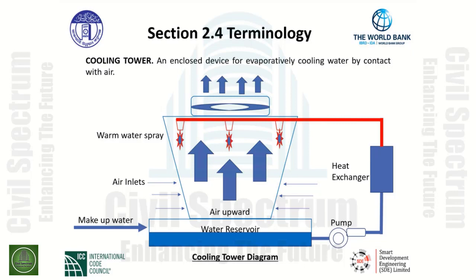The water reservoir must be at a certain level, not to be below the pump level. Therefore, because of evaporation due to the atmosphere, makeup water is required, and as you can see on the left-hand side, we do have a makeup water supply to keep the water reservoir at that precise level to keep supplying water to the process to cool down the heat exchanger and chilled water condensing water.